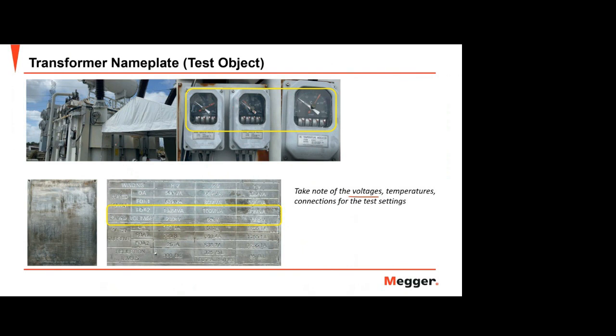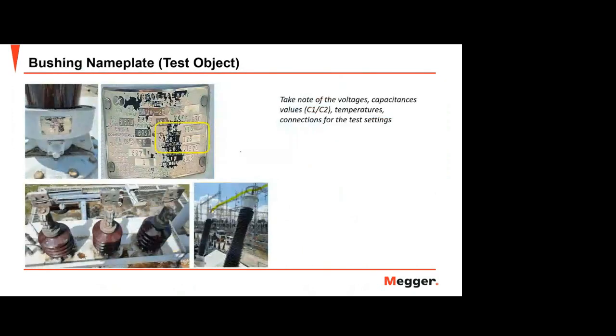So because that is an auto transformer and it has 3 windings, of course, I just forgot to put the picture of the 3rd winding here, but this is winding 1, winding 2, and winding 3. They also have the oil temperature sensor here or meter. Of course, for the connection, you need to short everything, the bushing, connect it separate from the tertiary. Because this is an auto transformer, of course, the bushings of the primary and the secondary should be shorted, everything. And then you can separately short also the third winding, the tertiary.